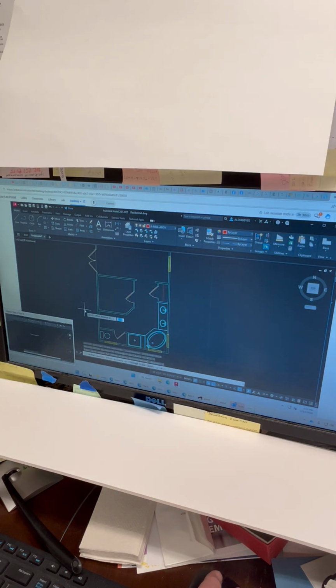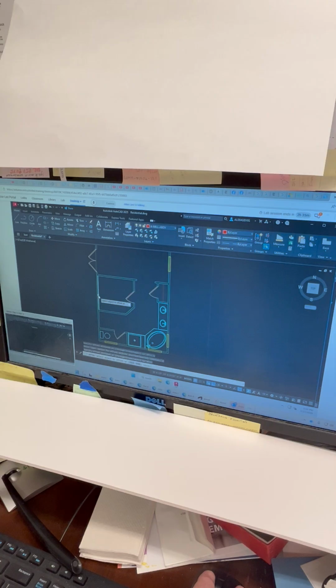Now, accept the default of 1 foot as your offset distance by hitting enter. And now offset this line here, this line here, and these are the shelves now of the walk-in closet, and they are on the correct layer. Okay?